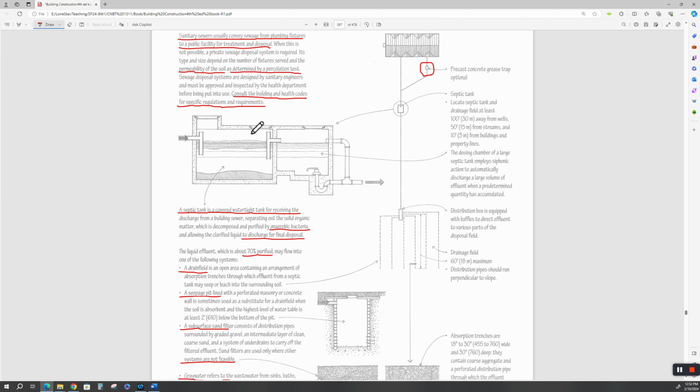It's an aerobic. So you're pumping air in here. You're not using oxygen like we do in the big wastewater treatment plants. We turn these giant concrete tanks into pressure vessels with a couple of inches of pressure with pure oxygen and mixers to mix all that. You're just using air, atmospheric air. So you're balancing the BOD, biological oxygen demand. I keep throwing that out there. I probably ought to type that in here for this video. It's BOD and COD. All right. Now in the police world, COD is the cause of death, but in environmental engineering, it's chemical oxygen demand. Okay, it's the chemical oxygen demand between the bacterial cell walls, and then the biological is what the bugs want to live on. Okay. All right.